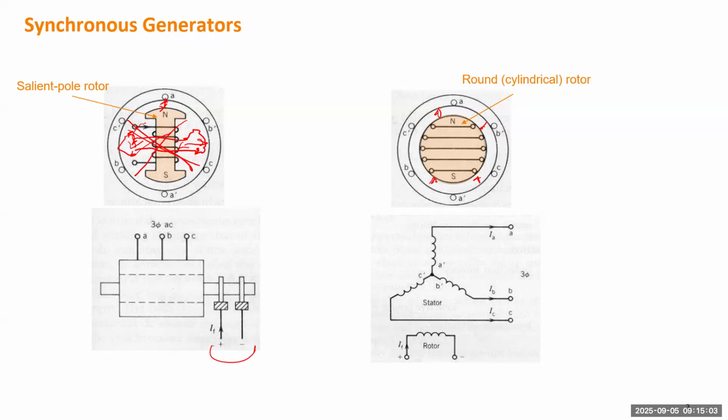If the 3 windings are connected in a balanced way, both spatially and temporally, which means they have basically identical windings, just laid out with 120-degree displacement, you can use this Y connection to simplify the circuit. For balanced conditions, you don't have the neutral wire, so that one can be saved. It's similar to the AC circuit we talked about in the previous section.